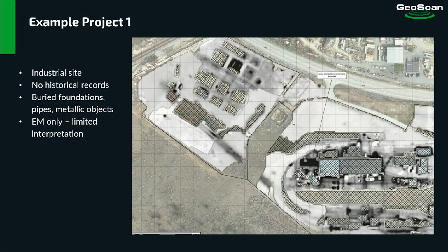You see the hatched areas, those are the obstructions or existing features such as buildings or known foundations or obstructions like debris on the surface or stored material. Everything that's outside and sort of black area, those are electromagnetic features, geophysical features that we marked out.